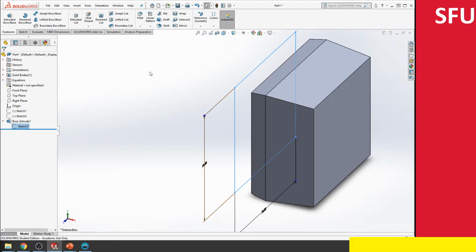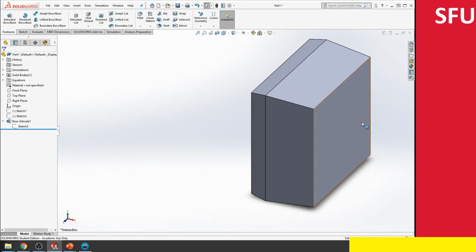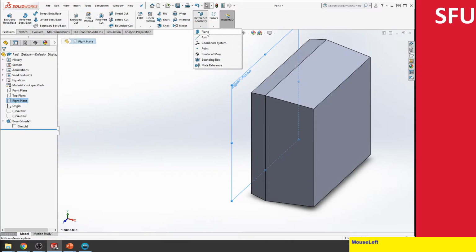and the entire shape is updated based on that. The other thing we want to look at is, instead of extruding by a particular distance, we can extrude up to a particular reference geometry, for which we need to create a separate plane. In order to create a reference geometry, I'm going to create one plane which is parallel. Since my sketch was created in the right plane, I'm going to create another reference geometry parallel to the right plane. So what I would do is click on the right plane and then click on reference geometry and plane.